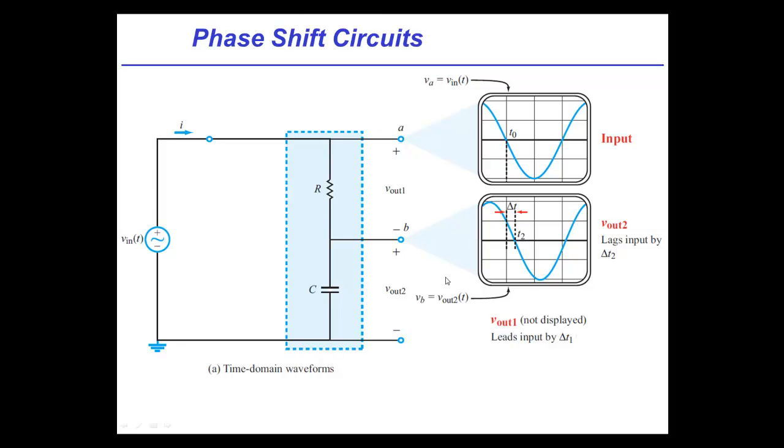Okay, what you're saying is that you've got this voltage source. Yep. It's going to be applied across these two elements. The current will be generated, of course. Right, and the current is the same throughout. Okay, and so the value of voltage across the resistor will have, of course, the same frequency as the input source, but the amplitude will change. But even more interestingly, in the case of the resistor, the voltage across the resistor will track with the current going around the loop. Exactly, because the voltage and current will be in phase. I see, but the current isn't in phase with the V in. Not necessarily. In this case, it wouldn't be because of the capacitor.